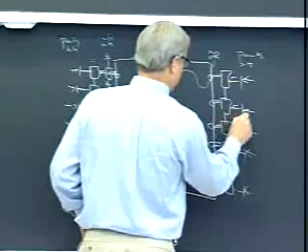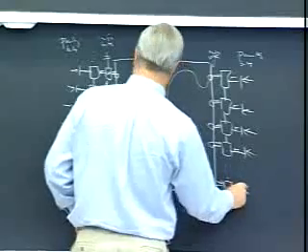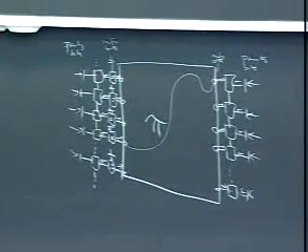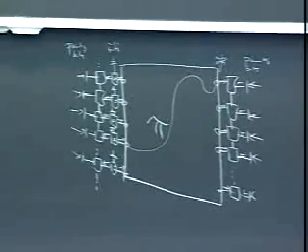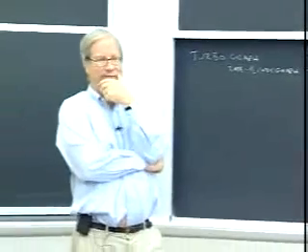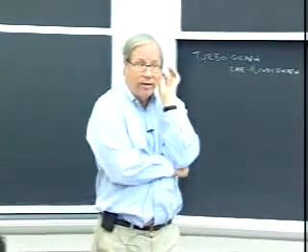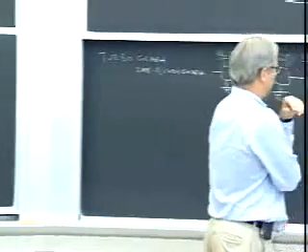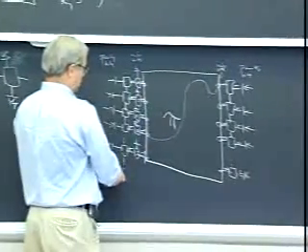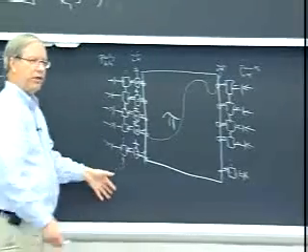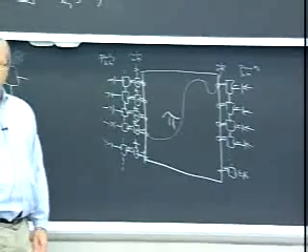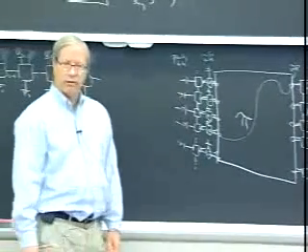And all of these are available too. Okay, somebody else. What's the next step? Somebody was just about to say it. Be bold, somebody. Trellis decoding. Trellis decoding, right. If we forget about that side and just look at what the sum product algorithm does over here, we're doing the sum product algorithm on a trellis, the BCJR algorithm.